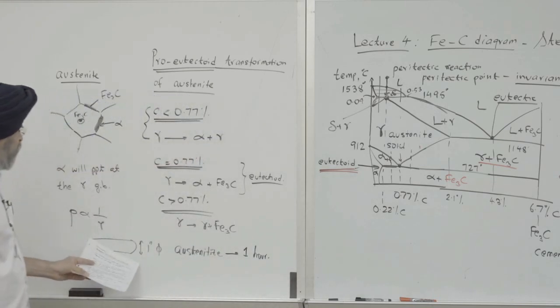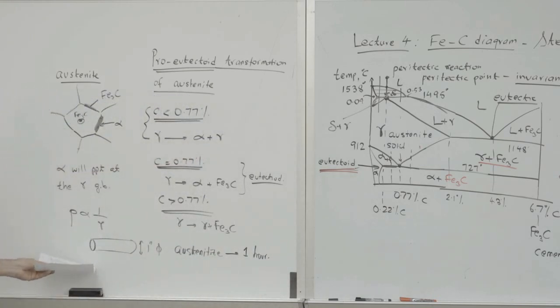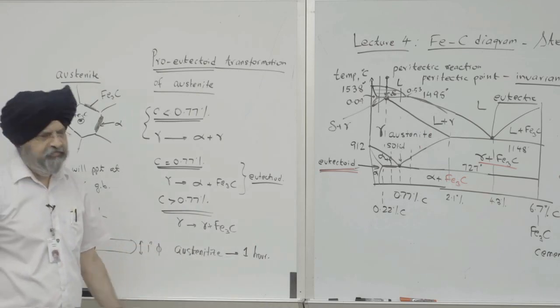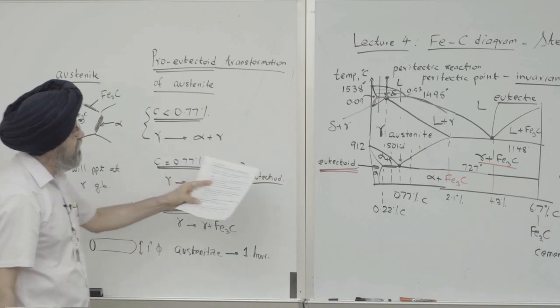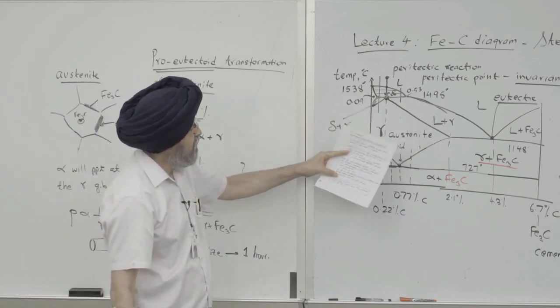That's the typical rule of thumb. If it's 2 inches, 2 hours, etc. That's the amount of time you need to make the steel homogeneously austenite.